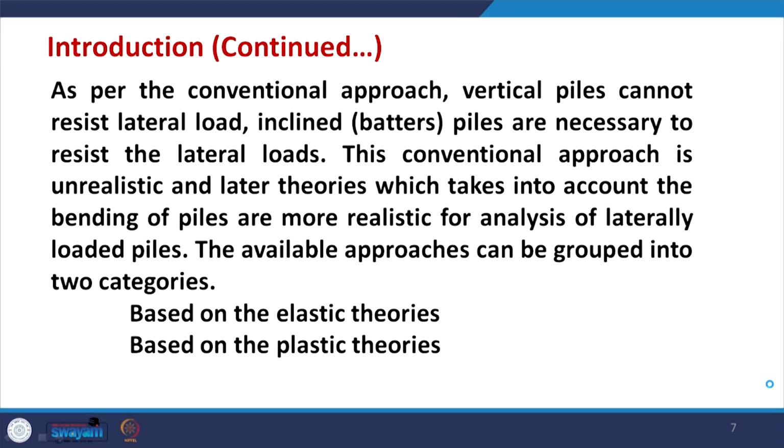It is not necessary to use an inclined pile, because the pile is supported by the soil, and whatever the soil capacity is, when you apply some lateral load on the pile, the soil will provide the support. That support is considered in the later theories, while in conventional theories it is neglected. So, later theories account for the bending of piles as well as the lateral support of the soil.